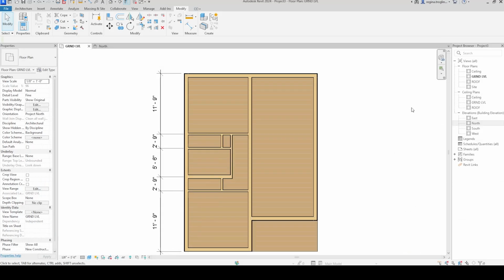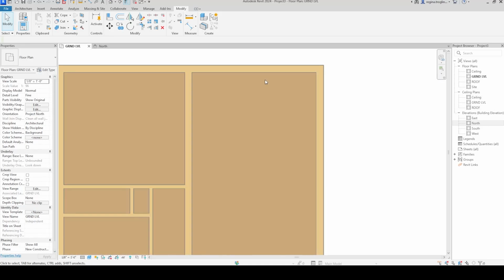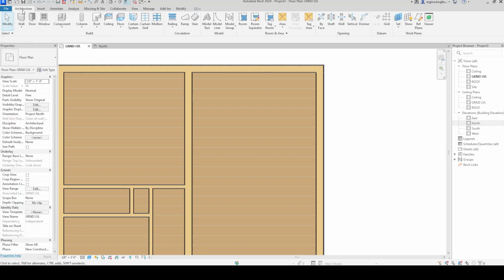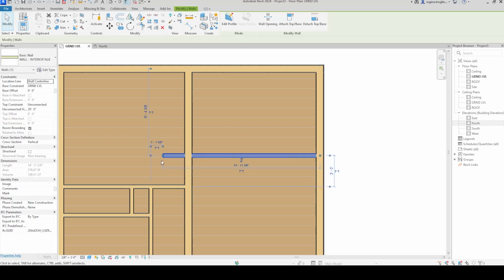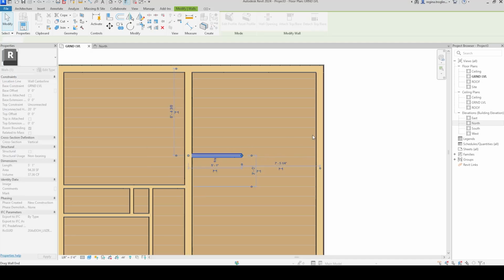So let's go ahead and draw that. It is not in line with anything. It's 8'9" forward of the back wall. So go back into architecture, do this. All right, so let's do the 8'9" dimension. We're going to grab the one corner and just drag this wall across. Totally fine. Blue bubble, drag it forward. Grab this one, drag it forward.